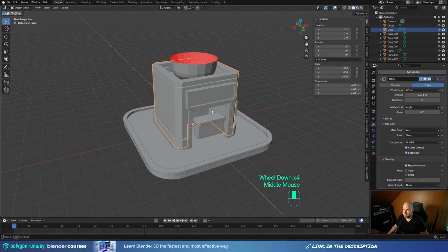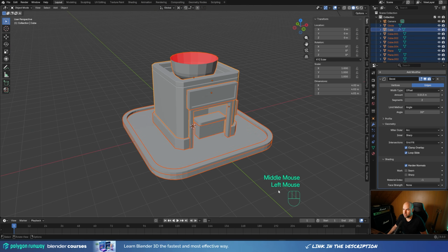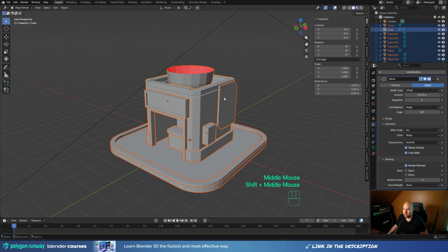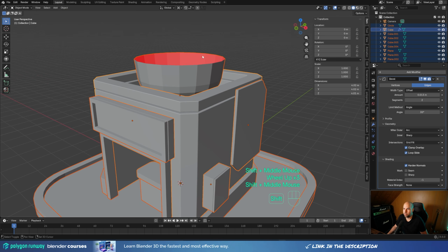And now let's just select everything. You can just drag a selection around your objects and then deselect everything you don't need. In this case, just the bowl. So let's zoom in a little bit. If you hold Control and just hit it with the box like this, you will see it deselects.